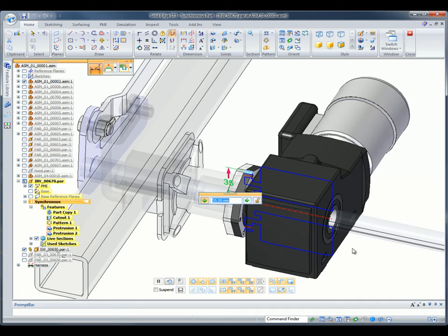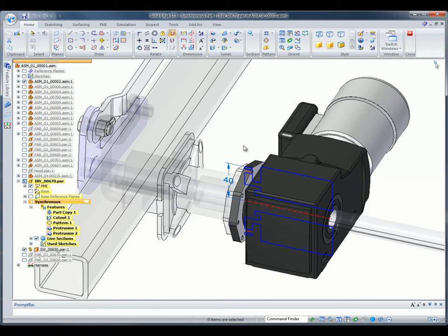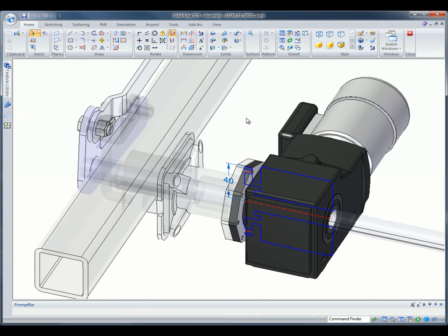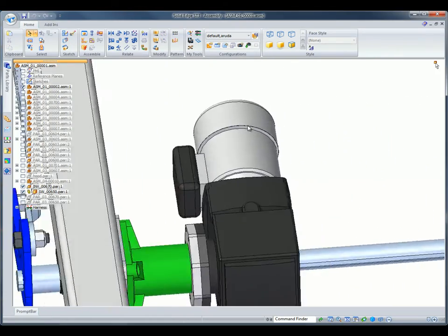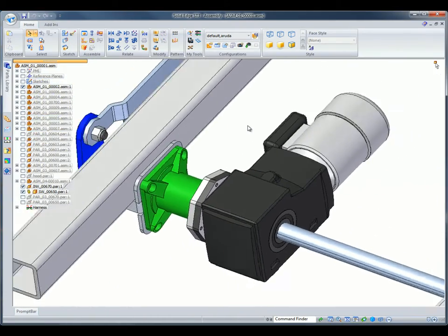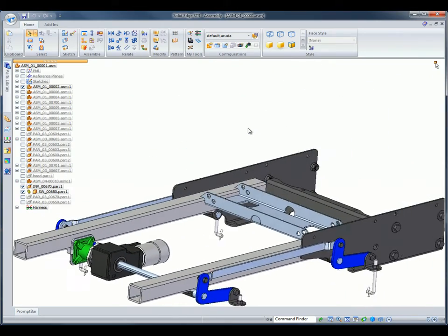We're going to make a cross-section edit change using a dimension that's driving the cross-section of our part. And by instantly making these changes, we can then update the file, and you'll see that our boss has been updated. So you can see it's very fluid now and very easy to make these changes inside of your assembly by using inner part copy.